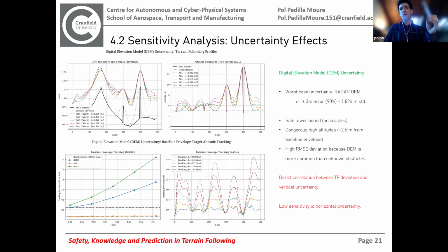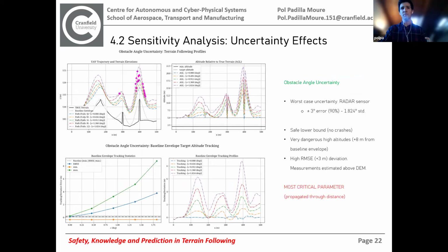But also, this effect, if using a radar DEM, is still not critical. You could still work with a radar DEM. You might just be flying sometimes 2 meters higher than you need to, but it is not such a bad performance degradation.